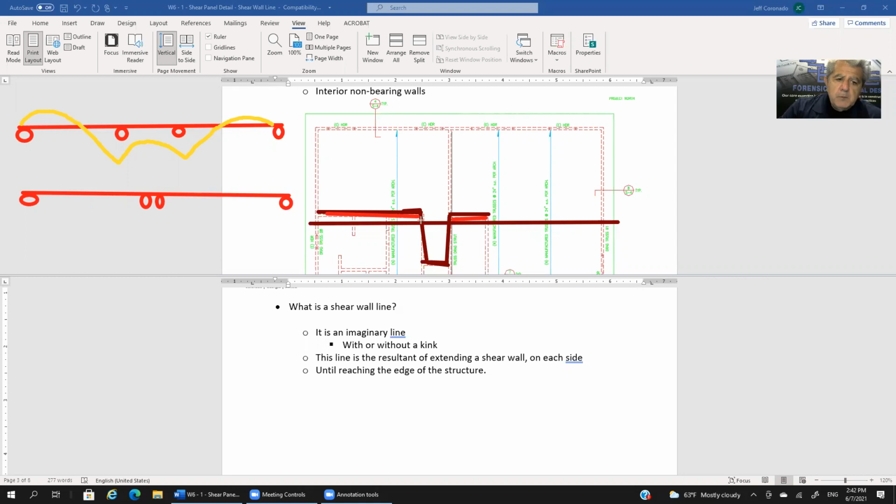you probably would look at that and you'd say, you know what? These two are essentially the same support, right? The behavior of this beam is not going to change a whole lot by having two supports so closely spaced together. The moment diagram in this case is probably going to be something like this. And it really doesn't get altered by the fact that there's two separate supports in such close proximity as compared to the other two spans.